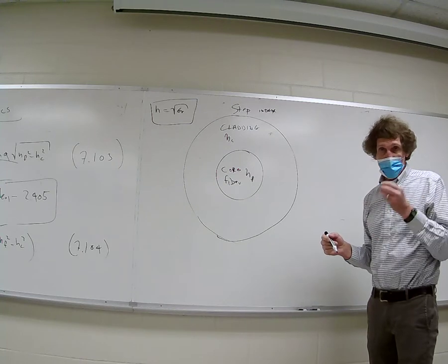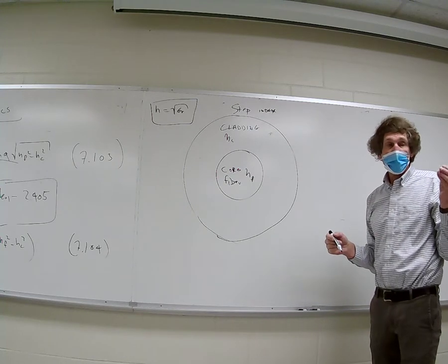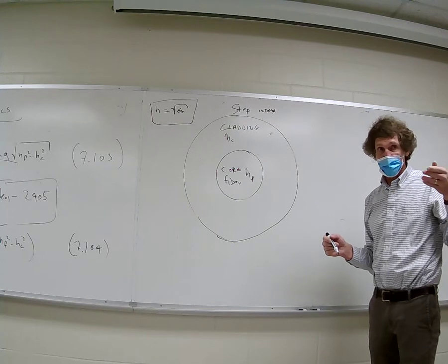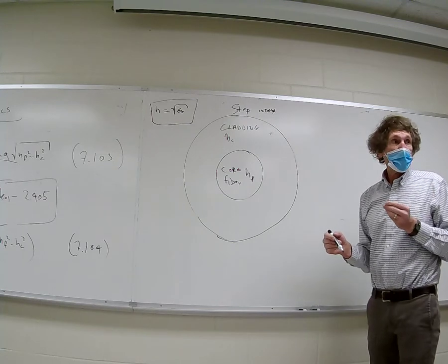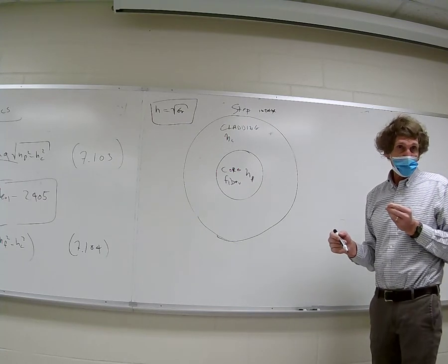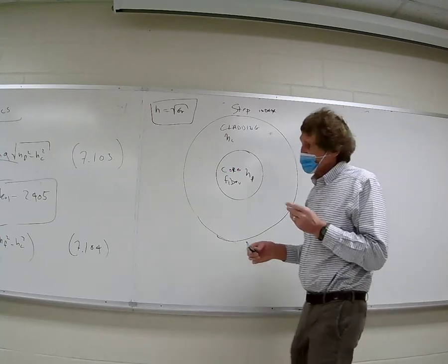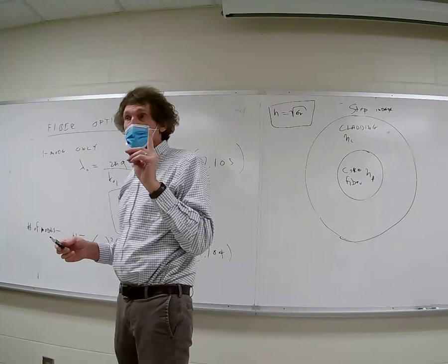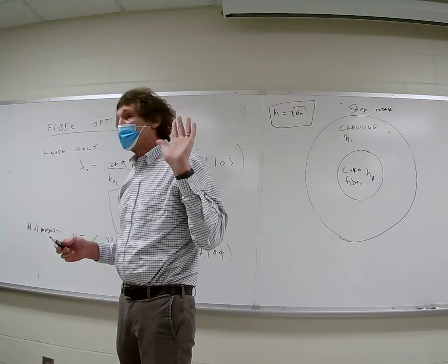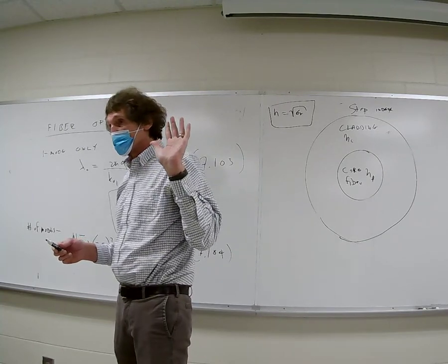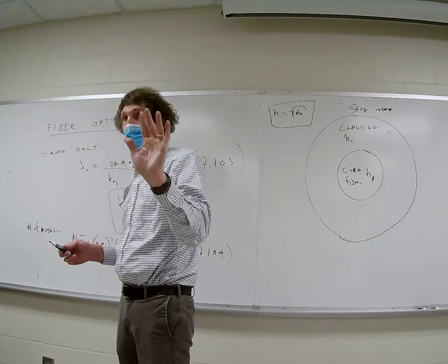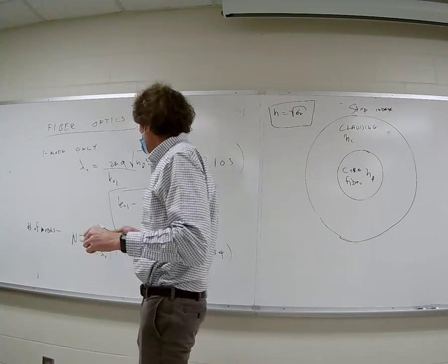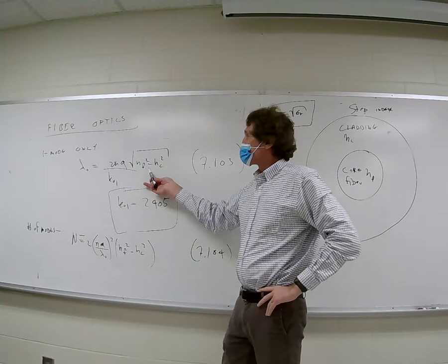Think of optical packets, where you're talking about the amount of photons per meter squared rather than the actual power density in watts per meter squared. This is important. When you talk about this, to get a single mode, only one mode, that's what you would want, because that means that all the energy that's flowing is moving at the same velocity. There's little dispersion. So this is what you want. For one mode only, this is the condition.